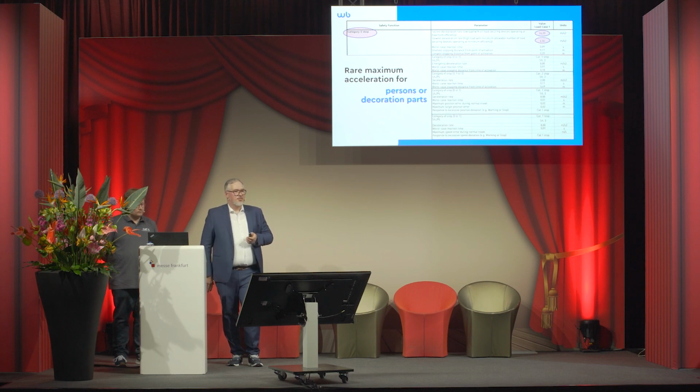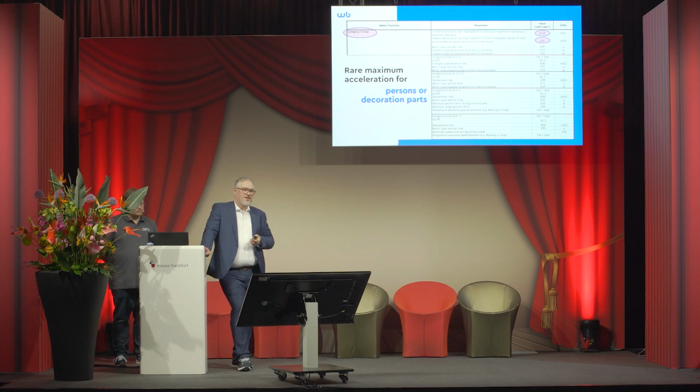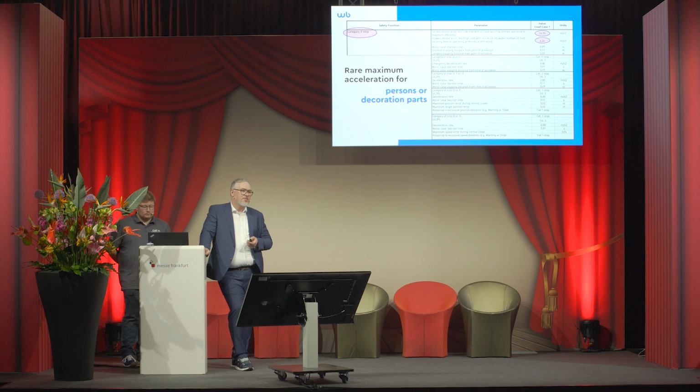So the category 0 stop can still happen. We cannot say that you never need to take this into account, but the possibility of this failure happening is rather low compared to the kind of safety function failures that you have in your daily operation, for example a slack rope or overload scenario, things that just happen from using the machine in its intended use.